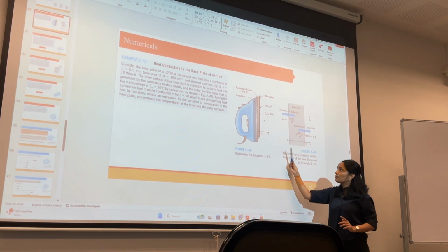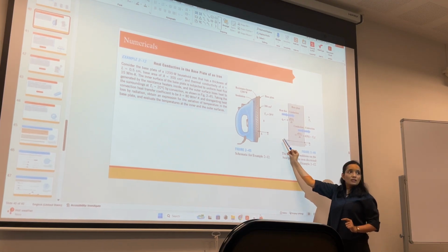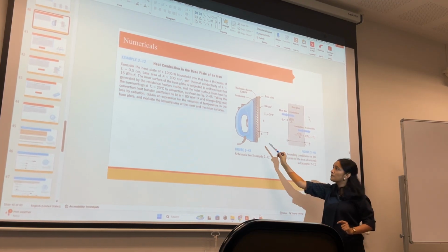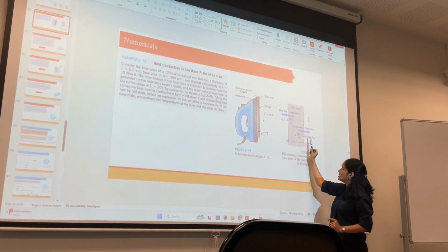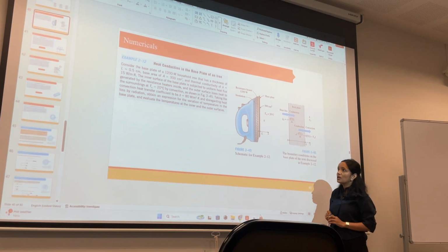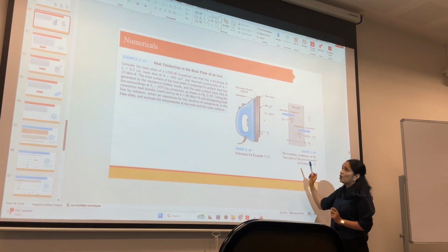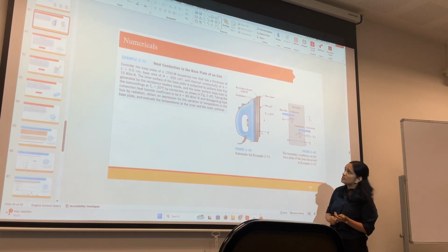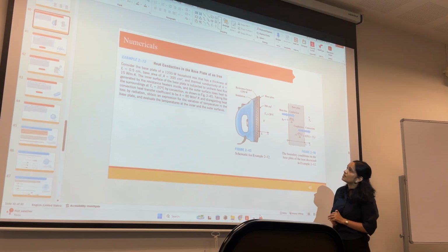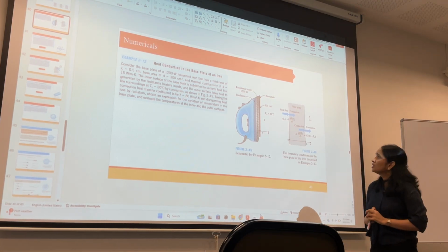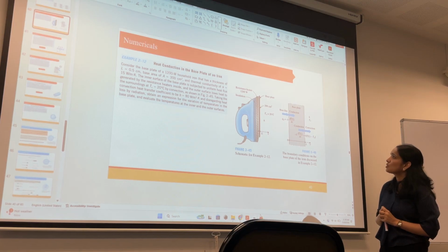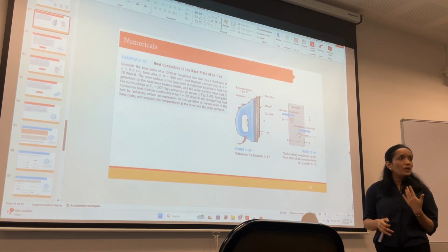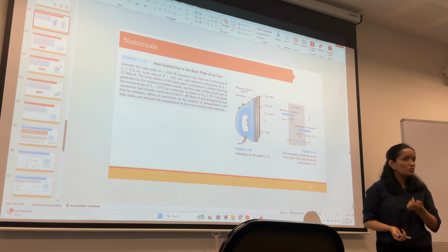Heat transfer that is happening from here to here, heat flux, right? This is subjected to constant heat flux. Inside conduction, outside convection. Okay. Now tell me for plain wall when the thermal conductivity is constant, right? What else is given? Steady state, right? It's steady state. And thermal conductivity is constant. Which equation for the plain wall are we going to use?